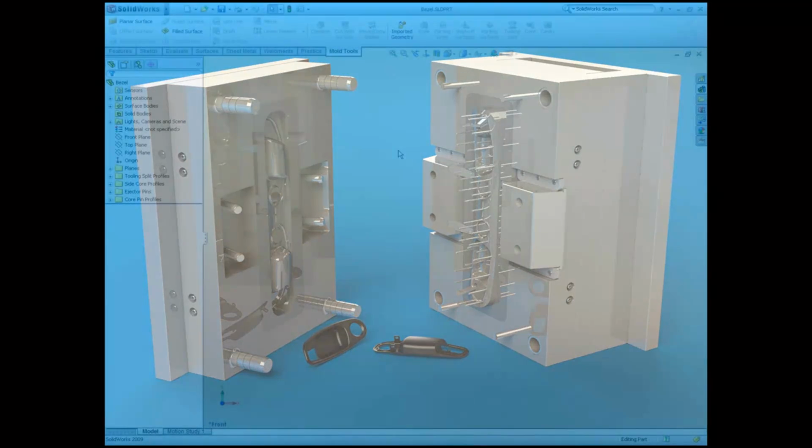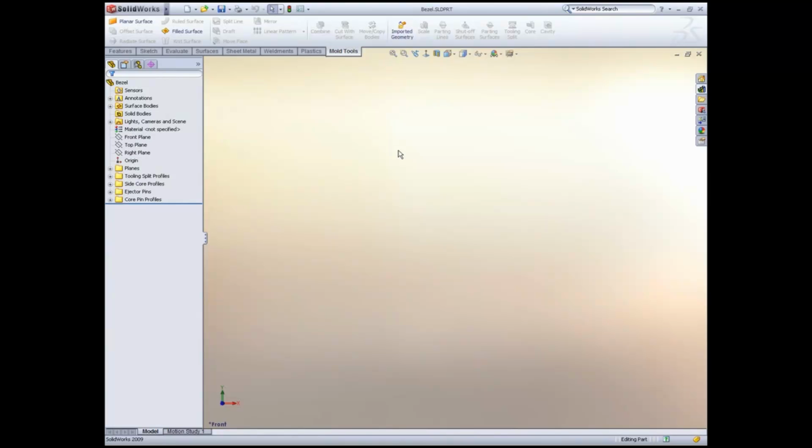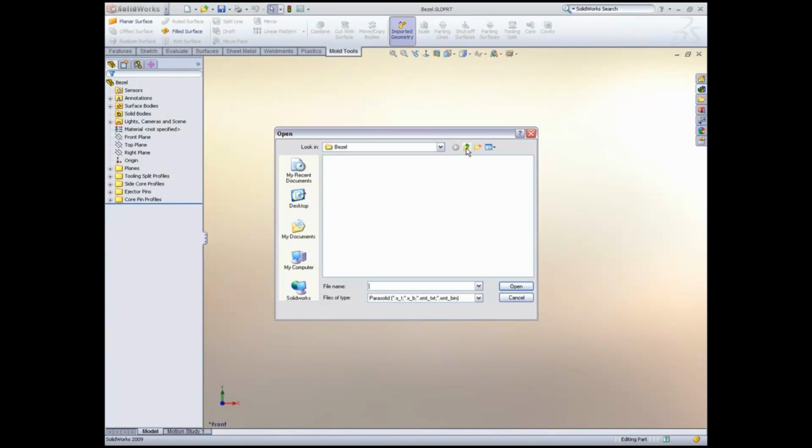Working with different customers requires flexibility when it comes to accepting different file formats. SOLIDWORKS imports a variety of different 3D CAD formats, some of which are neutral formats such as IGES or STEP, and some are native CAD system formats such as ProEngineer or Unigraphics. The file format that toolmakers have been forced to work with over the years is IGES, and geometry errors are commonplace.